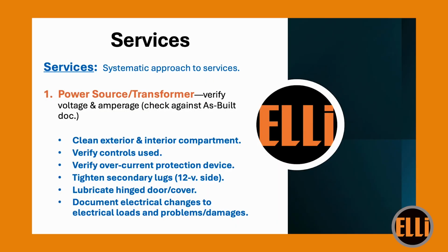Again, we talked about, let's say you open it up and you see a fried frog inside the transformer, whatever it is. You make a note that, hey, rodents or insects or amphibians, whatever it is, are getting inside the transformer. Maybe you can find a way to seal that off better so that future issues don't occur. Okay? All right, let's move on.